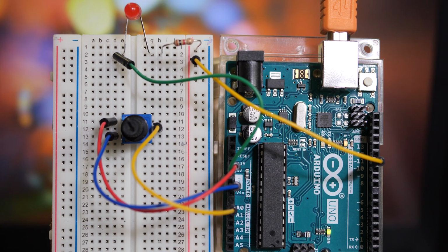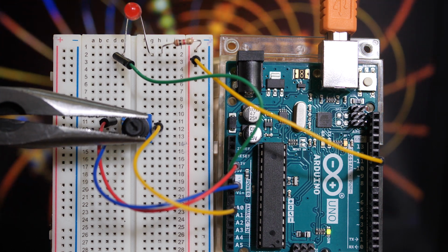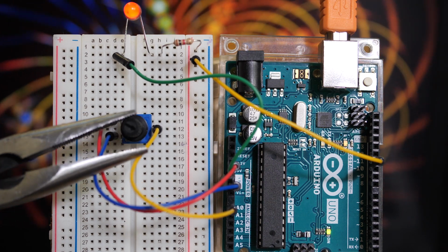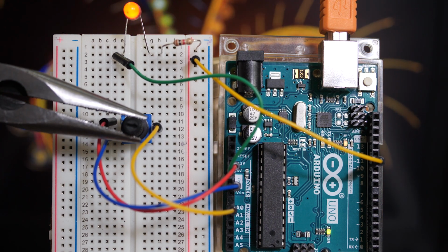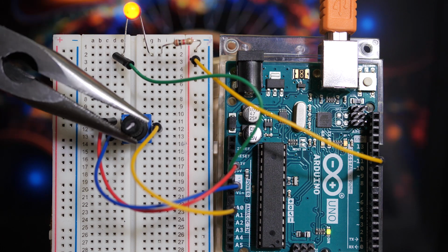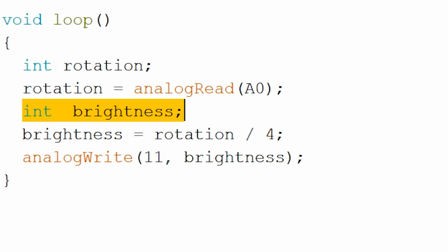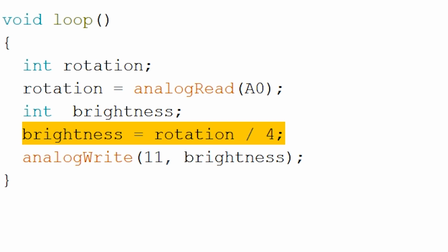That is where the potentiometer comes into play. As you remember, when rotated, it outputs an analog signal, which is then divided by ADC into 1024 stages. So, by rotating the knob, one puts number from 0 to 1023 into that box. The fourth line of code allocates yet another box in Arduino's memory. It will store brightness data. In order to understand what brightness we have, we need line number 5. It says, look in the box rotation, grab a number and divide it by 4.